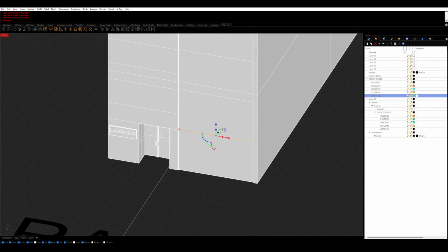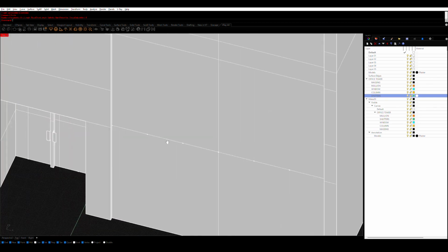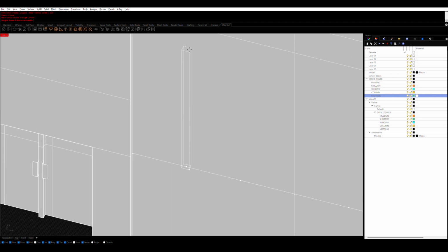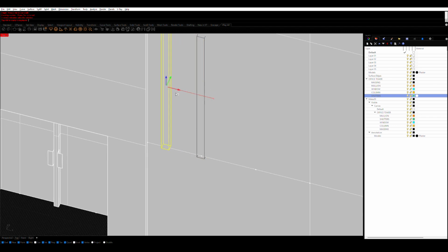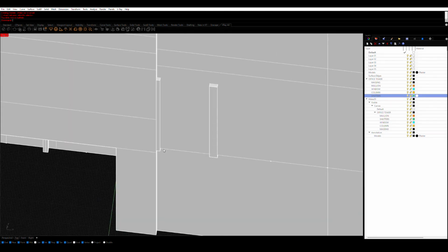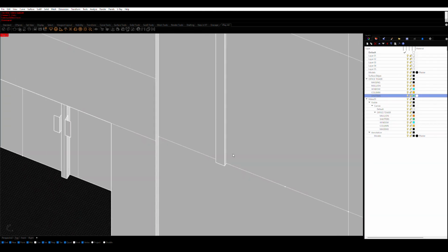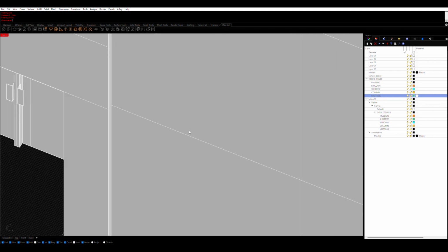That looks okay. And one thing we'll want to be careful of is that we can't simply divide this into 6 and then make our mullions from there, because if we create our mullions using the center of these points, once they reach the edge, these mullions will actually be halved, and part of it will actually go into the wall on either side.